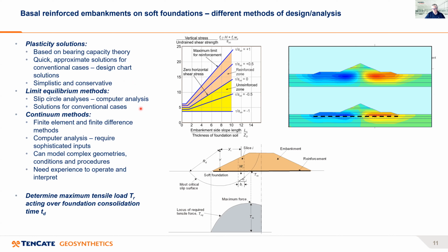The next type of method we have available are these limit equilibrium methods, which are really slip circle analyses. And of course, these days they're all run on computers, which make them all very easy. And in diagram form, this is effectively what's actually being worked out. You have the embankment with the basal reinforcement, and we use the computer to do the slip circle analysis.